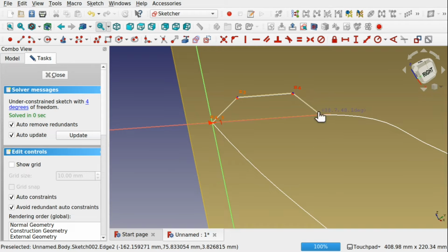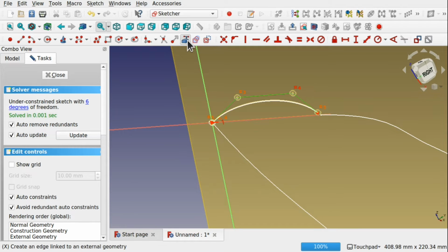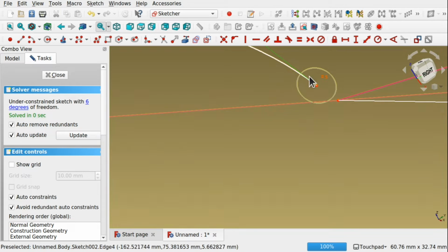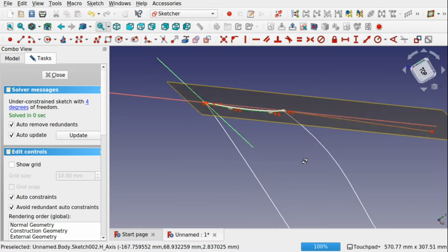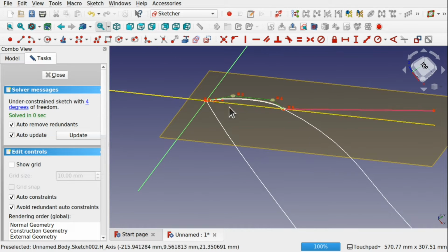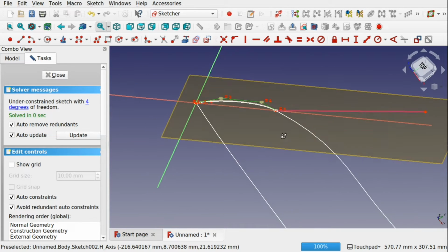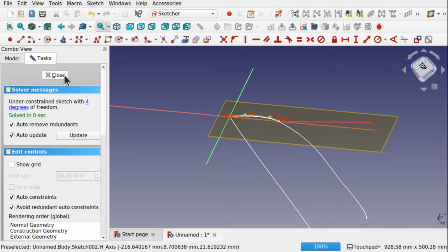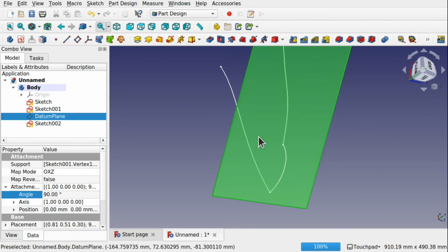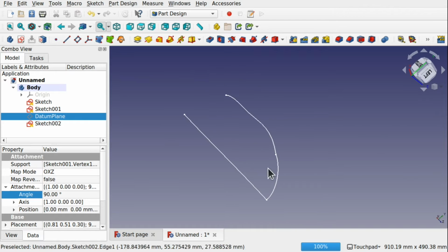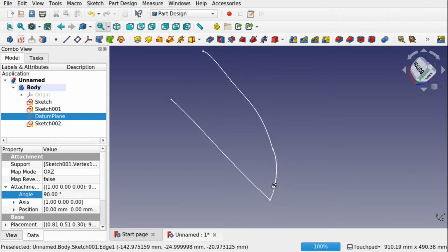And you can see I can attach up by pulling in geometry like so, and using that point and that point, and making a constraint against them. So that makes it an easy way of attaching between two vertices like so. Obviously there's many ways you can actually attach datum planes, but that's one reason to use a datum plane, is if you've got geometry that's hard to get to and you can get to those actual vertices.